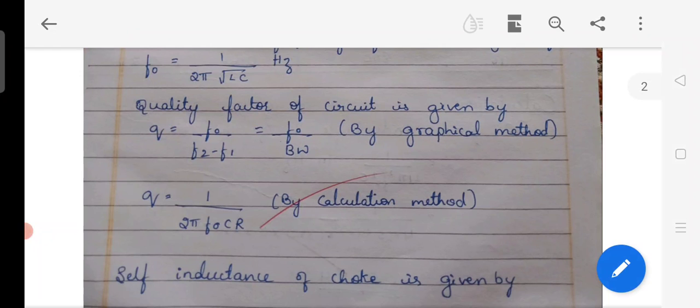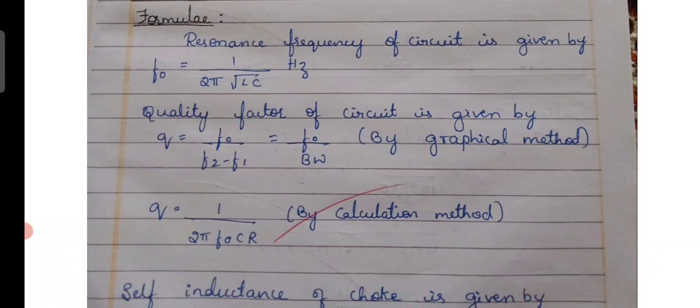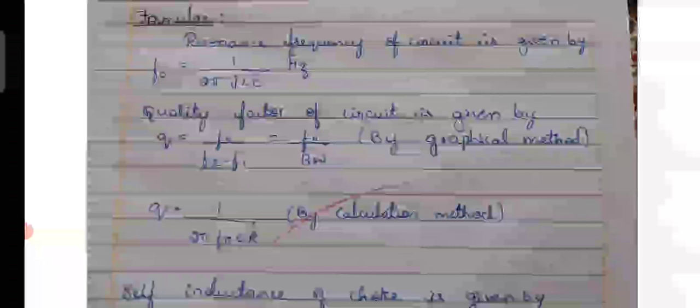We had discussed cutoff frequency in the last experiment also, which means maximum gain divided by root 2, therefore we are going to obtain some value. The graph is going to be bisected, or cut, by that value, and we are going to obtain a frequency.